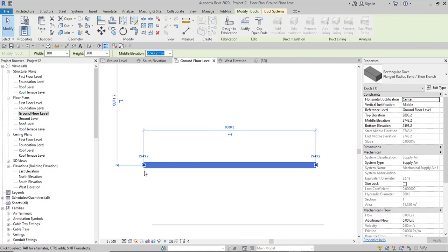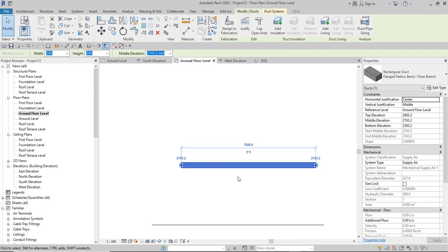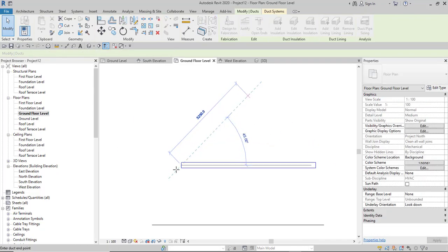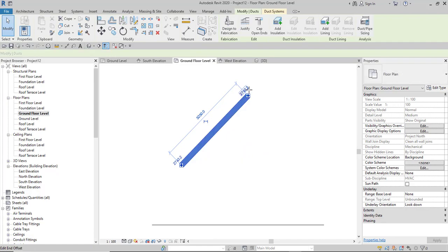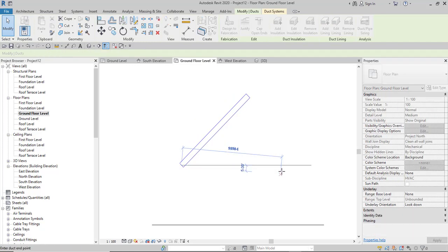You can hold these drag points and move them to any new position you want. So long as you have a start point and an end point, the Revit object you've drawn will follow where the start point is and where the end point is. So you can hold it and drag it anytime to wherever you want it to be.